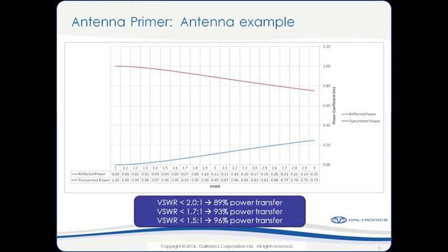So when you mount, maybe the question was about whether the VSWR of the antenna is impacted when you mount below, through, or above? In that case, we're able to show that we still meet the requirements on the datasheet. So if we spec 1.7:1 in the high band, we will meet 1.7:1 in the below, through, or above configuration.